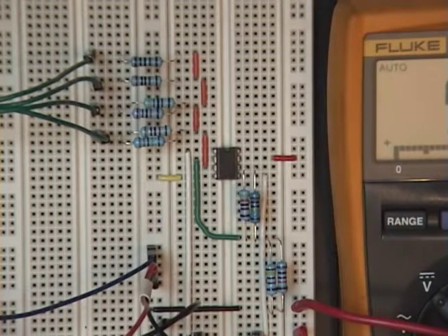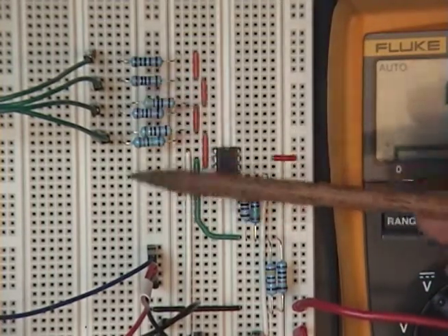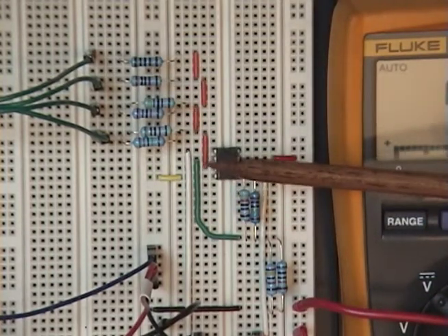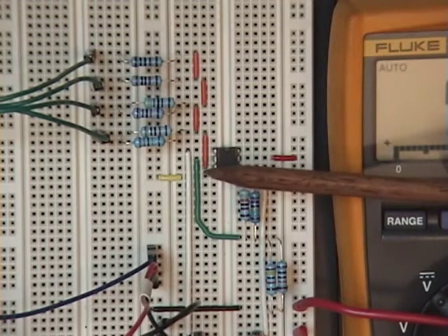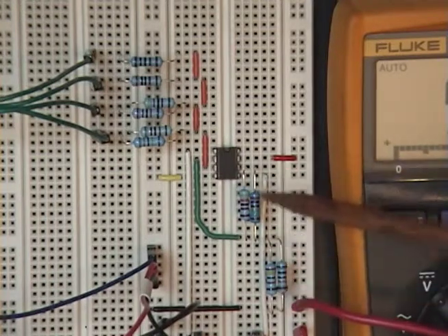Well, we know that the maximum value I can express at the input is all ones, or 15 decimal, and what that generates at the output of the resistor ladder is the value of logic 1, which we've seen as 5.05 volts. So the gain we want in the amplifier is something that will convert 5.05 volts to 15 volts. I already calculated the appropriate resistor values for the feedback divider.